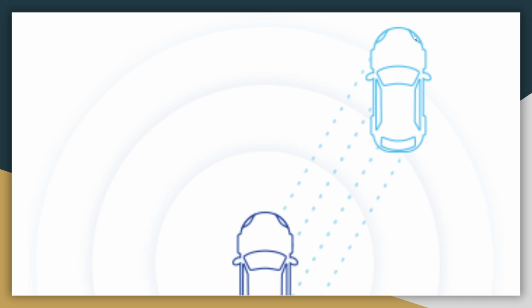So it won't necessarily see all these things. This headlight over here, the right headlight, the right window, none of this will be seen. Only whatever is in this field of vision will be seen. And since I'm using an RP lidar, which is a two-dimensional sensor, it's going to give me only the boundary of this car and not even a three-dimensional view of it. But in the end, you're going to generate points all over it, and then the points will be reflected back, right? When I'm trying to map the other car. So that's again a point cloud.